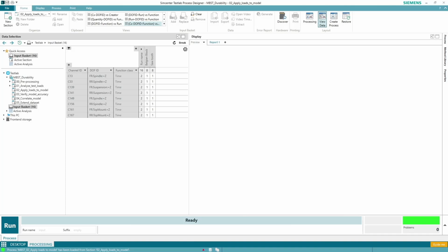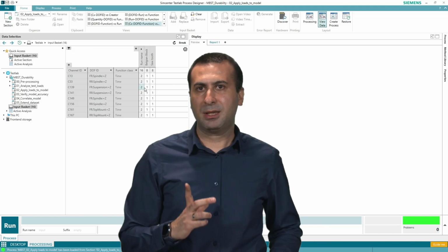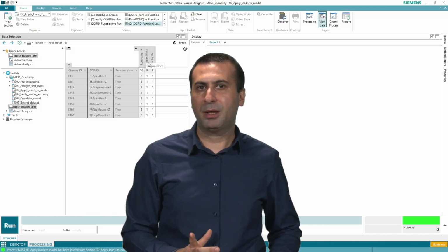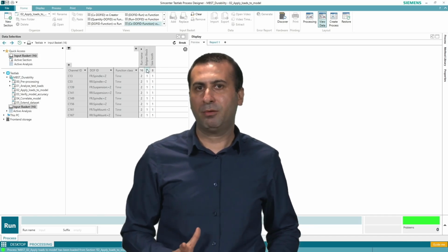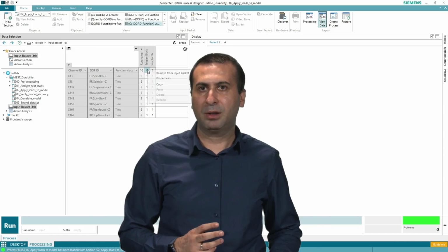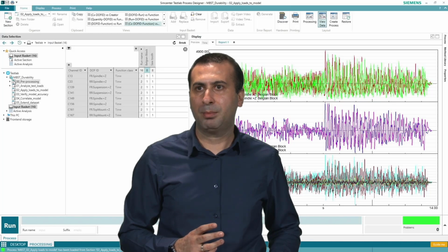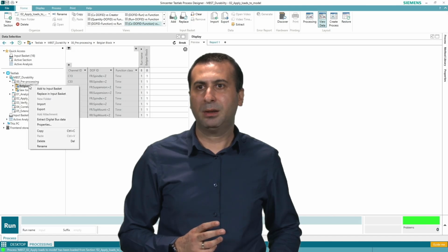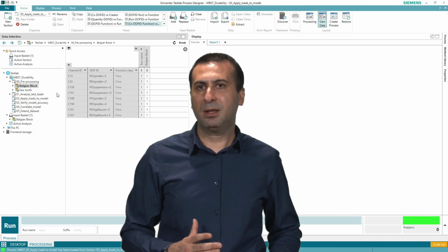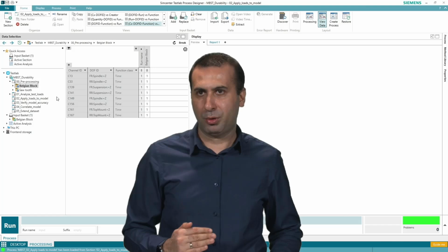So it's here. From the previous section, you might recall that I had 16 different channels on my input basket, but I just decided to proceed with only Belgian block because I already identified that Belgian block is more damaging for me. So it's not necessary for me from now on to use the sawtooth. So what I will do, I will click on only the Belgian block run and replace, sorry, I need to go to my pre-processing again where I stored all my runs. So Belgian block is over here. I will right click and replace an input basket. Which means that all the rest are now removed. So I only have Belgian block as an input to my further process.